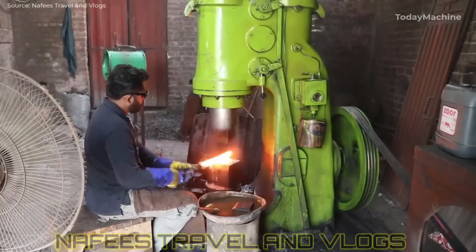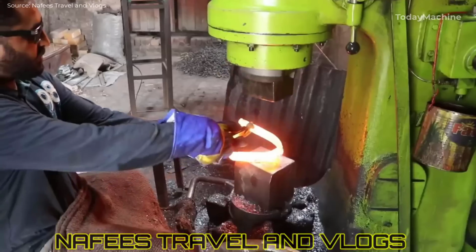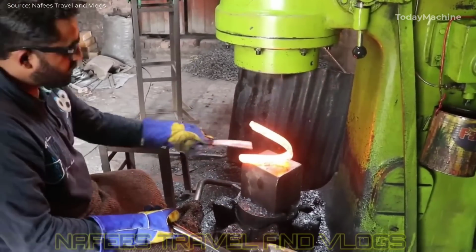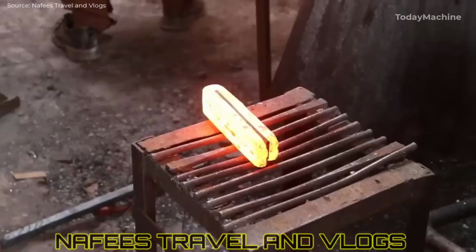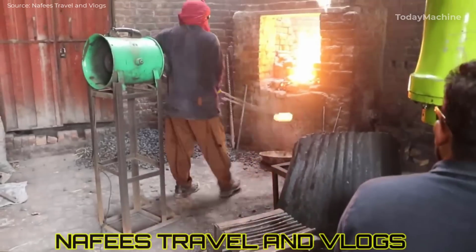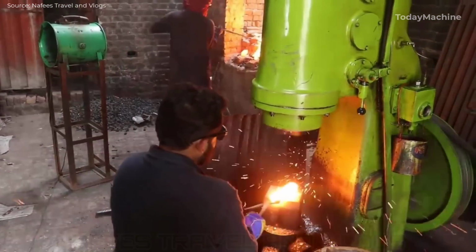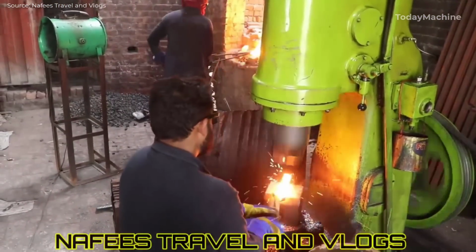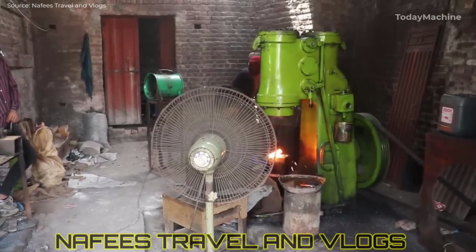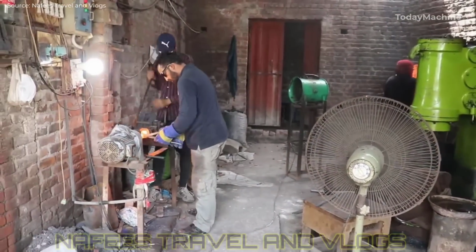The process of crafting a traditional sword by hand is labor-intensive and requires a high level of skill and precision. It begins with selecting the appropriate steel, which is often sourced locally. The steel is heated in a forge to a temperature of around 1,200 to 1,300 degrees Celsius, 2,192 to 2,372 degrees Fahrenheit, at which point it becomes malleable enough to be hammered into shape.